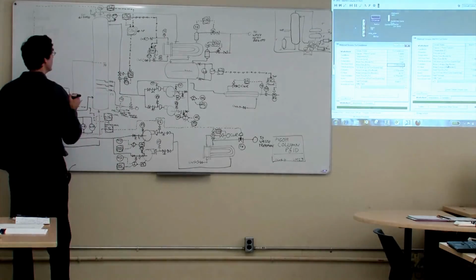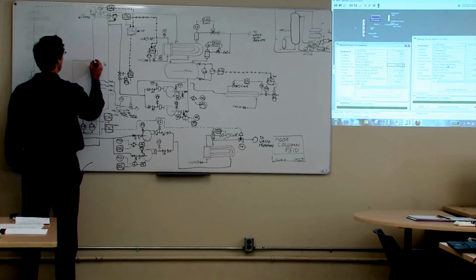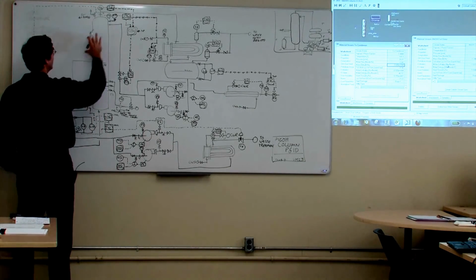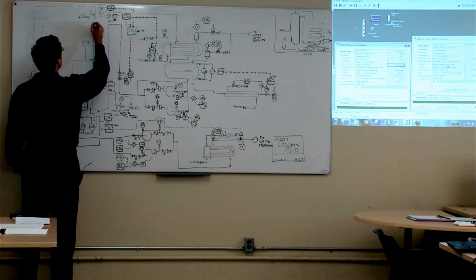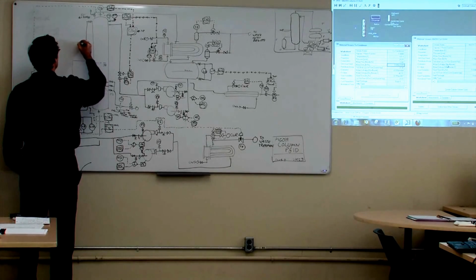The other thing that's nice to have is you might want to measure the differential pressure across the tower. So you can do the whole tower, or you can do it in sections. Usually it's often done in sections, so above the feed and below the feed. So I want a pressure differential indicating transmitter. I need a valve, flange, and a valve like that, and I want to pull that into the DCS, pressure differential indication, like that. That's handy.